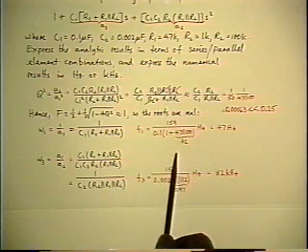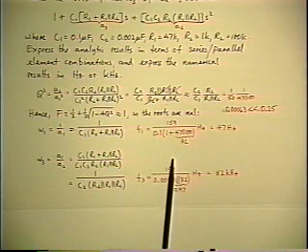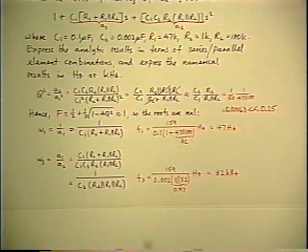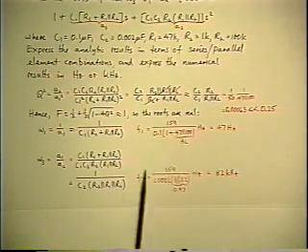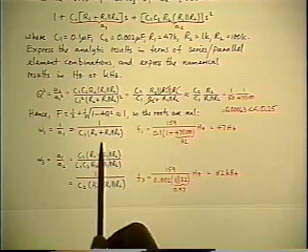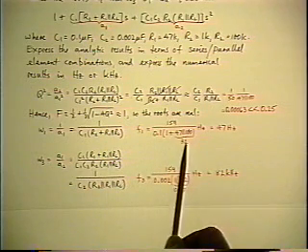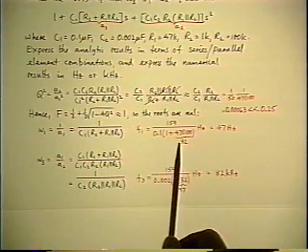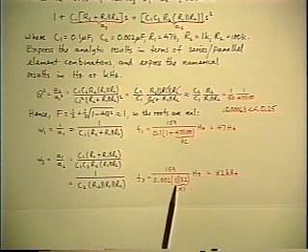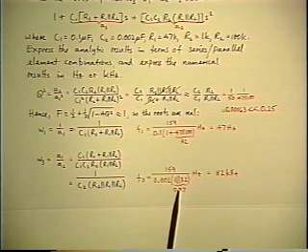However, the important part about this, as I emphasized before, it's worthwhile writing down the intermediate numerical result before you combine all the terms, because that way you retain the usefulness of the low entropy version. And when you do that in this case for the two results, you see that the resistance that determines the omega 1 is principally the R1 parallel RL. The R2 is almost negligible. In the other case, since it's a triple parallel combination, the R2 is the dominant one because that's much the smallest of the three.